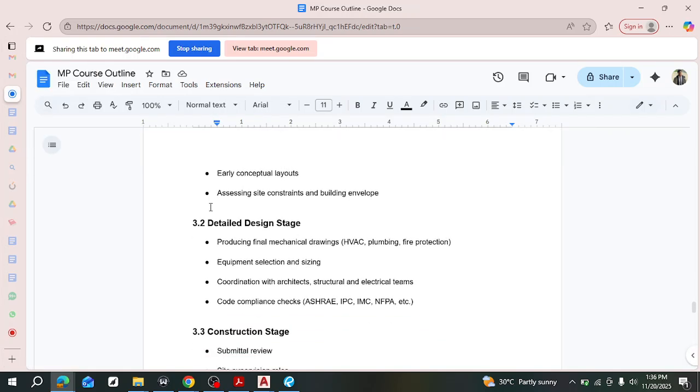Okay. So that is just an idea of what layout looks like. You have in your mind, this is where I want to place this here and not here. Also when you're piping, you know where the pipe is going to run. One thing I do is that I don't like my sewage lines to run through the house. If something is leaving the bathroom, I like it to exit the house as fast as possible. I don't like it leaving the bathroom, entering a bedroom and then flowing through a kitchen. So I do it in such a way that it leaves the bathroom last, because of the kind of solid waste that leaves the bathroom. That is just the way I do my layout.